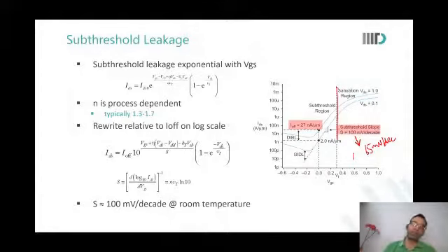Yeah. So let us go a little beyond what we were talking about in the last class, or possibly in the last office hours, where we were discussing the availability of electrons in the conduction band. Do we realize that at all times at room temperature, there will be some electrons in the conduction band? Yes, sir. So if there's an electric field applied somewhere, those electrons will flow. Yes, sir. That is leakage. Even if the device is off, there will be something in the conduction band.